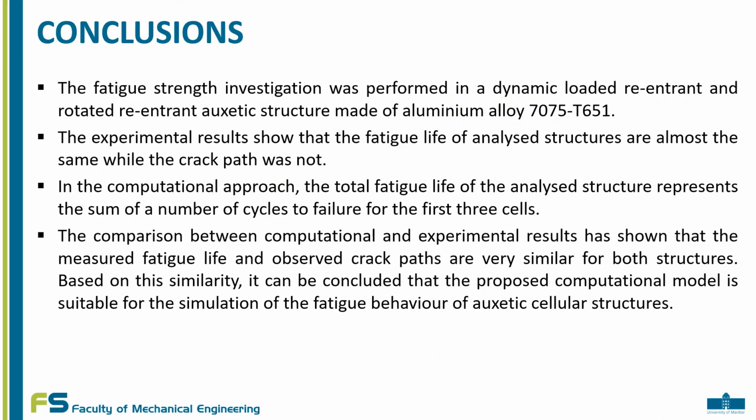Conclusions. In the scope of this research work, the fatigue strength investigation of dynamically loaded re-entrant and rotated re-entrant auxetic structures was performed. The experimental results showed that the fatigue life of the analyzed structures is almost the same, while the crack path was not. Based on this, we can conclude that the unit cell's orientation does not influence the fatigue life of the analyzed auxetic structures, but only affects the direction of the fatigue failure path.